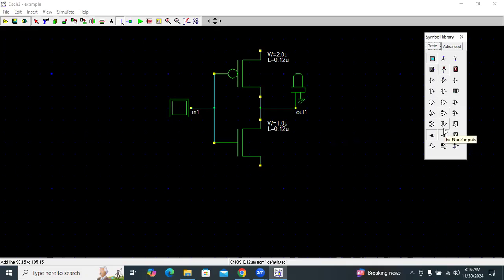So as your first trial experiment, now I have designed a basic CMOS inverter. The basic CMOS inverter will have both a PMOS transistor and an NMOS transistor. Then we have to make a connection for the input, and the result will be connected to the output. So for the PMOS transistor, I am searching in the library. It will be in the second line from the bottom. I just drag and drop the component. So PMOS and then NMOS.